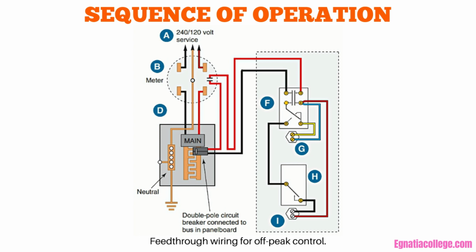When all of the water in the tank is cold, the upper element heats only the water in the upper half of the tank. The upper element is energized through the lower contacts of the upper thermostat. The lower thermostat also indicates that heat is needed, but heat cannot be supplied because of the open condition of the upper contacts of the upper thermostat.